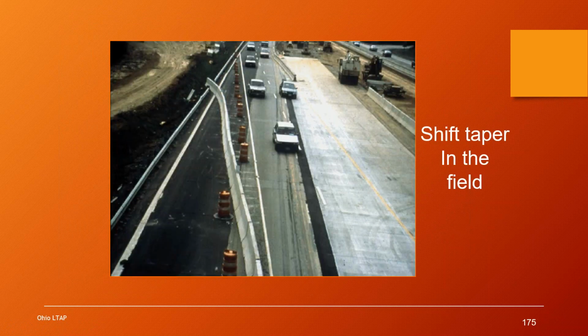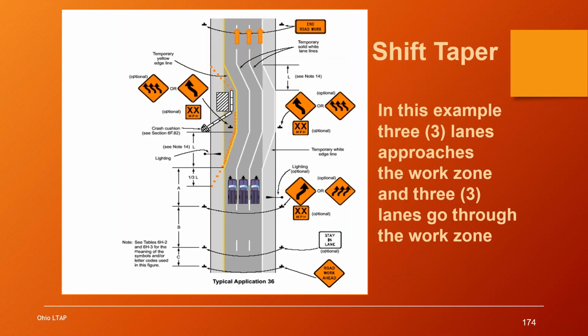So here's a picture from one of these projects. Here we have the right lane closure for the southbound right, and then we're using a shoulder over here to run traffic on temporarily. So we shifted them over. And again, if you're going to use the shifting tapers, you got to have the shifting arrow signs to go with it. So in this case, we have a sign here with 3 shifting arrows on one sign because there's 3 lanes of traffic to shift back.